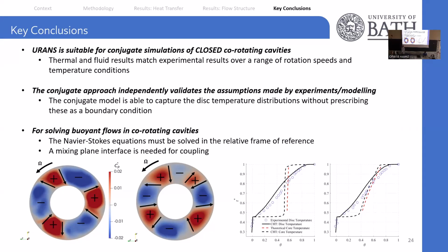Do you still have to use the Y+ values again? Yes, we still have all of the mesh at Y+ of 1 for all of the interfaces.